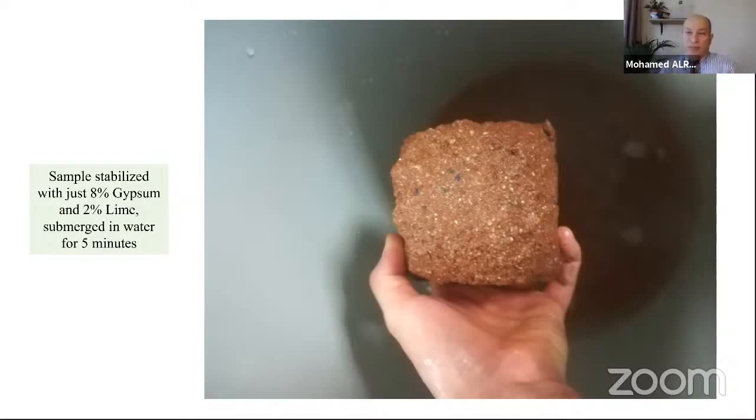Okay, maybe gypsum will increase the bearing capacity of the soil under dry compressive strength only. In comparison to the non-stabilized samples, gypsum increased the bearing capacity from 25 kilogram per square centimeter to 45 kilogram per square centimeter. That's it, under just dry compressive strength. And we didn't reach more than 45 kilogram.